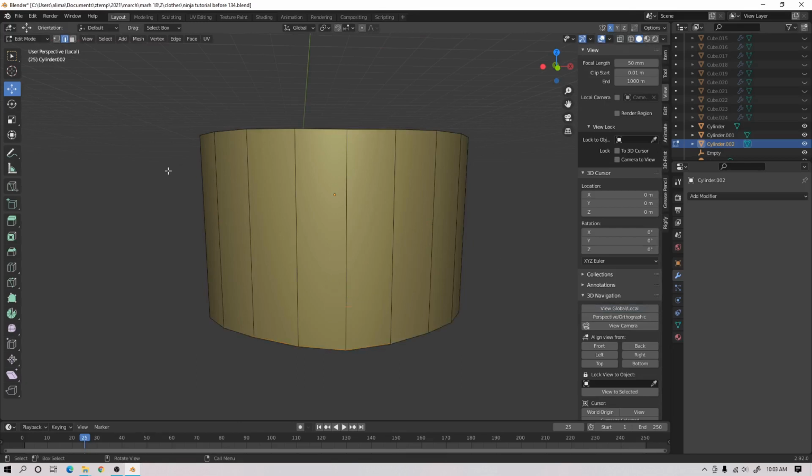So what we're going to do is press K first. K activates the knife tool, right? We want to cut through the front of what we see, but also what we don't see, which is the faces out of view, right? So when you press K, you'll select just what's visible. We're going to press Z. Wait a second, is that right? Yeah, we're going to press Z.